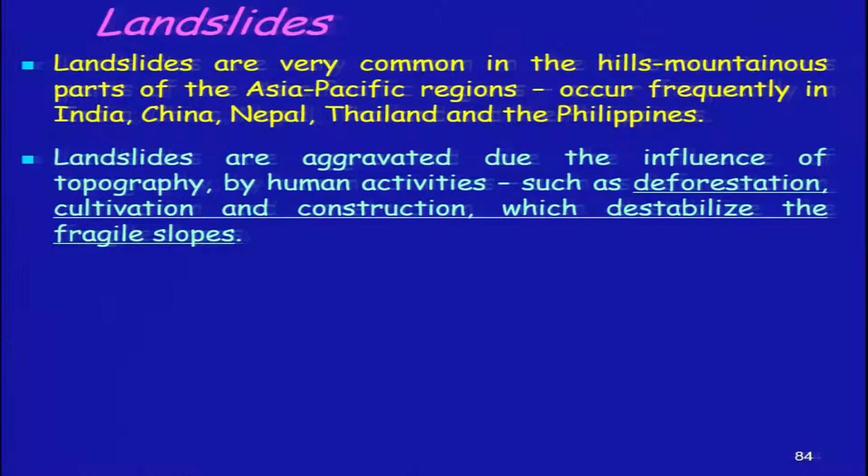Now, topography, as we were talking about, we would say that if we have a slope, then this area is likely to have a slip, if other conditions are fulfilled, like you have heavy rainfall, or you have weak zones or weak material sitting on the slope. Those are prone to landslide. And the landslide will occur when the sediments lose their shear strength or the capability of holding themselves on the slope. Another is deforestation.